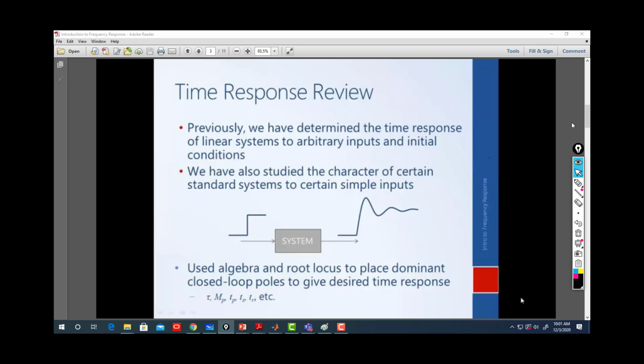And how did we find the parameters of the controller in order to shift the open loop poles to a closed loop pole location that meets my desired response? We did that using algebra, like system identification, as a starting point if the system is not canonical, and if canonical, then it meets our response exactly.